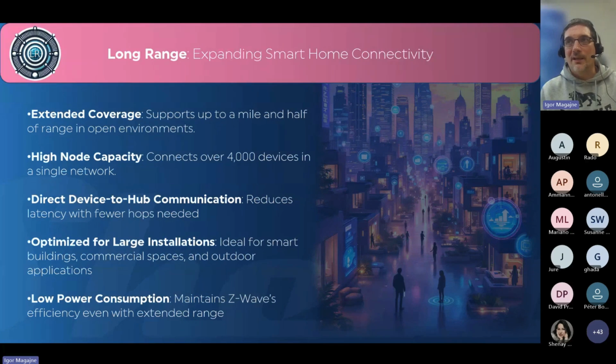When you're updating, flashing, let's say, a mesh device with long range firmware, no problem, it will go. The first thing that will probably happen is that it gets disconnected from the network, because it's completely different, even if it's mesh, a different firmware. We tried it, and yeah, we just got disconnected. The second thing is that you then don't have the QR code. The QR code is of a mesh device, so you cannot include long range with a QR code from mesh.